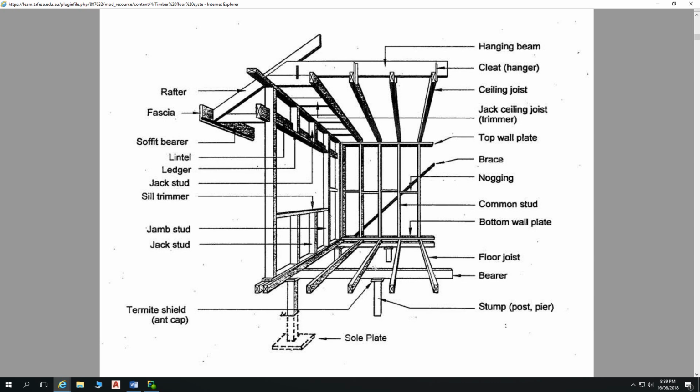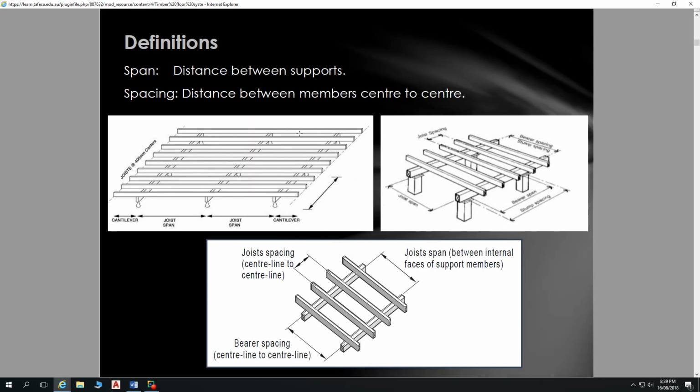And this was an old building. It had been trashed by tenants. It had suffered a great deal of damage. But the fact that it was a platform floor as opposed to a fitted floor tipped the scales in favour of it being a far more economical choice to replace the building than to repair it. That can be a drawback with platform flooring because your flooring goes underneath your wall frames. But that's pretty much the only drawback to it. It makes things so much quicker and easier on site.